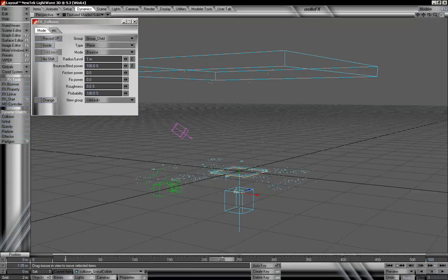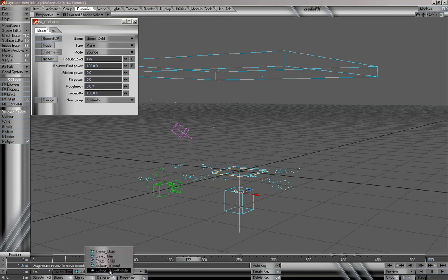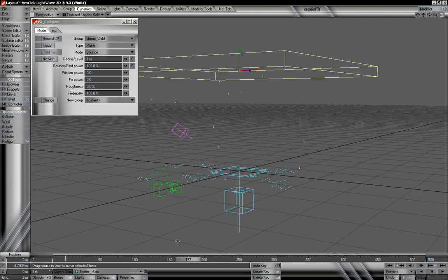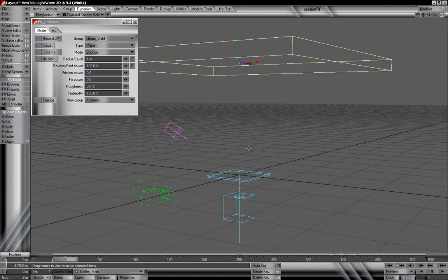And this is very helpful for when you're working with hypervoxels, because if we want to have our first emitter, we'll take a look at emitter main, being one type of hypervoxel effect, and then when it hits the ground we want it to change, but we don't have to go into envelopes and really changing the scene a great deal. In order to achieve that, we can have new emitters created with new hypervoxel effects, and that'll also really help us with birth rate times and make it much easier to create different scenes. And we'll go ahead and apply some hypervoxels to that in just a sec so we can see that a little bit better.